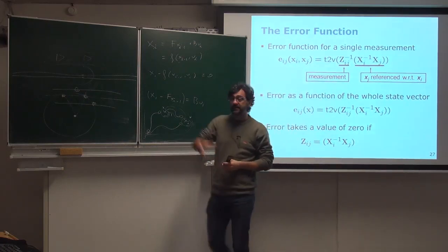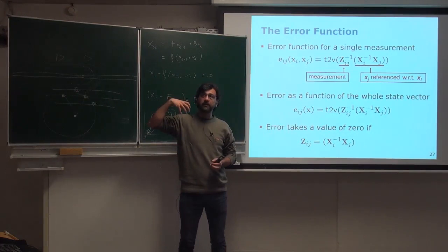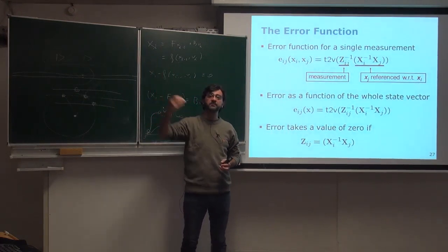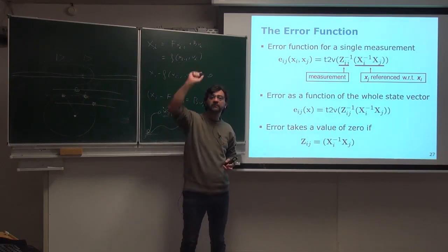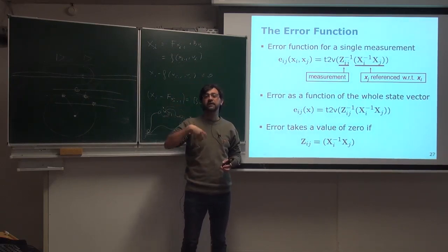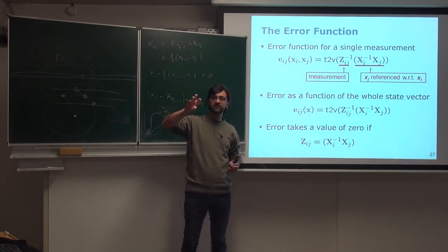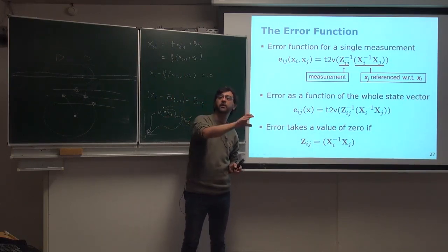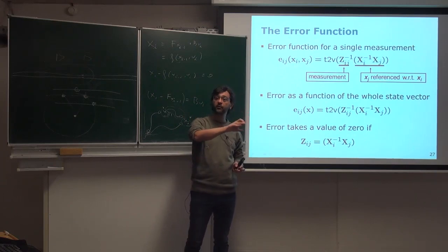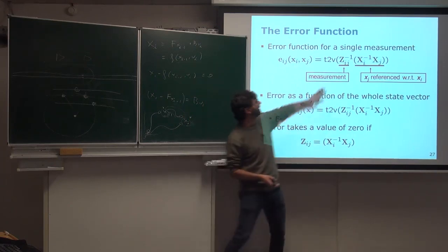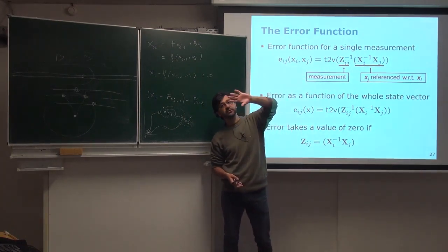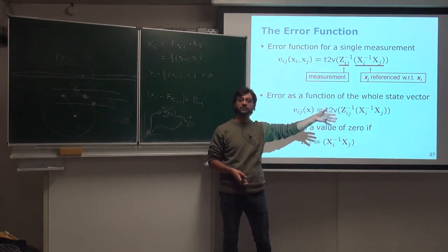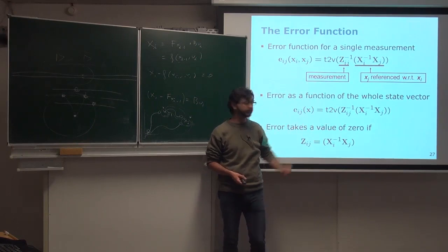It takes a transformation matrix and gets back the vector representation, which basically means if we have zero translation, we will have a zero in the vector, and if we have an identity as a rotation matrix, it will end up in a zero angle for the angle part. So it's just a way of going from a transformation in terms of matrix to a transformation in terms of vector representation.